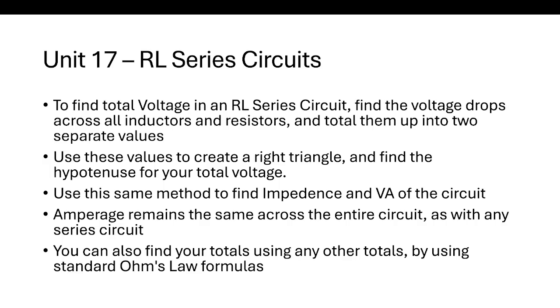You would use the same method for impedance and volt amps, but your amperage obviously remains the same across the entire circuit because it is a series circuit. And you can find your totals using any other totals by using standard Ohm's law formulas. So for example, if you don't feel like going through this method to find your impedance, but you have your amperage and your voltage, or even just your amps and your watts, or your VA, or your volts and your VA, you can do your standard Ohm's law calculations to find those.